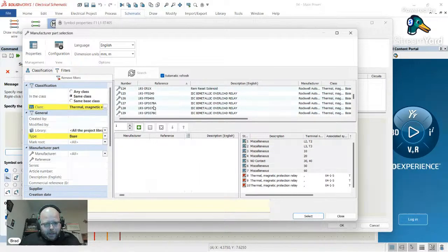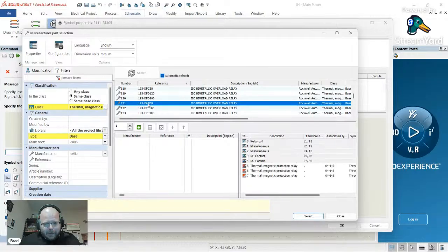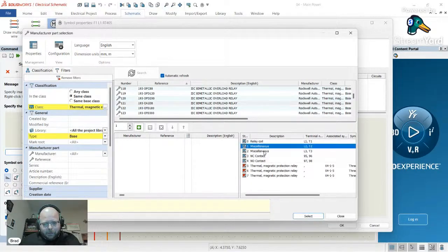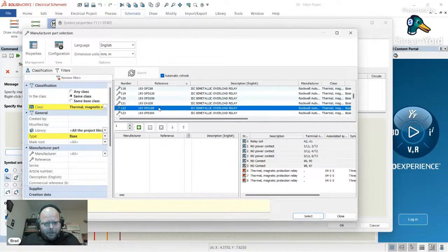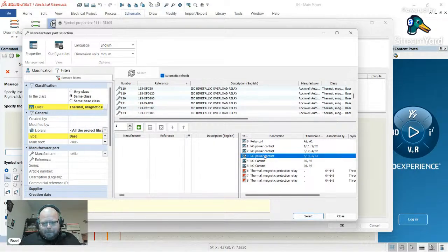This also may be Allen Bradley just not using the right circuits, like miscellaneous. L2, T2. So that's only a 2-pole anyway, so that's not good for us. I mean, this is a 3-pole with some extra contacts, but it's not thermal.